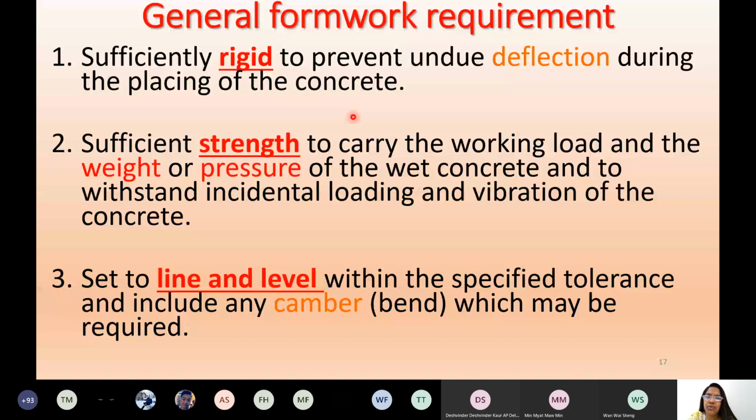But the main and foremost advantage is to achieve the strength of the concrete. Only if the concrete is strong enough can it bear the load. To achieve the strength of the concrete, it should be cured. No curing, no strength. It's like a loose material, soil material. It won't take any load, right?